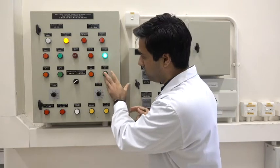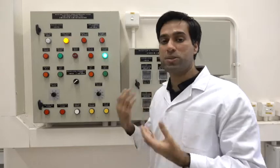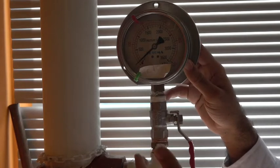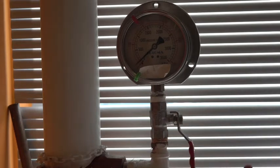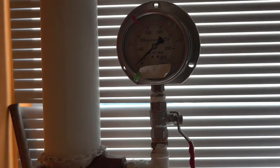You can start the pump from here, and you can control the speed. This is a pressure gauge where you see the reading of the required pressure. In this experiment we will be using 13 bar, which is again a very high pressure to produce water mist. This pressure gauge is only for the water mist system.